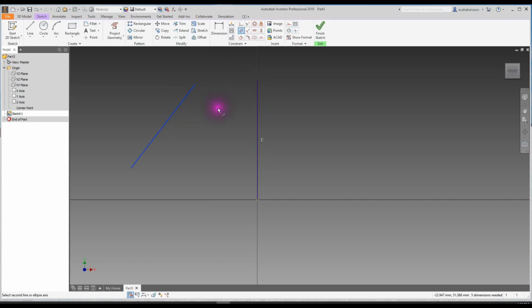All right, you've been thinking about it. So let's try it. There we go. This one line will move because this line is already constrained and cannot be made parallel to the other line. Sometimes things may not move or constrain exactly the way you want, and then you have to think about what you have done and what constraint may already be interfering with what you're trying to do. So try this a bit on your own, and you get a feel for how things work.